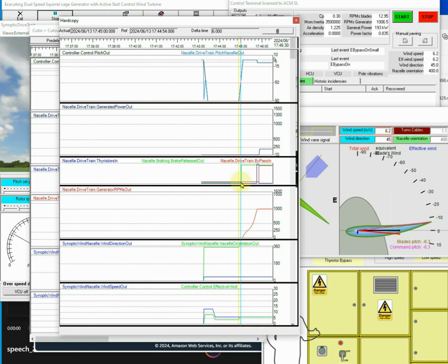There are two regions. Eventually, the RPMs reach the vicinity of the 1000 value, the synchronous speed of the small generator. This is a key moment. The generator axis is rotating near its synchronous speed, and its stator winding is disconnected from the grid. For production, the conditions are as follows. The stator must be connected to the grid, the RPMs must be above synchronous speed, and there must be a rotating magnetic flux in the air gap. This transition is handled by a specific device, known as soft starter. Read the tutorial for a detailed discussion about it.